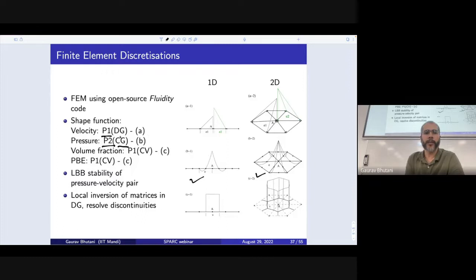We can have discontinuous Galerkin, where at a given point, depending on which element you are in, you can have different values. This is very useful to handle discontinuities. Like if you have a front of temperature moving, no diffusion, only advection, purely advective equations, which are hyperbolic in nature, they are very effectively handled using discontinuous Galerkin methods.